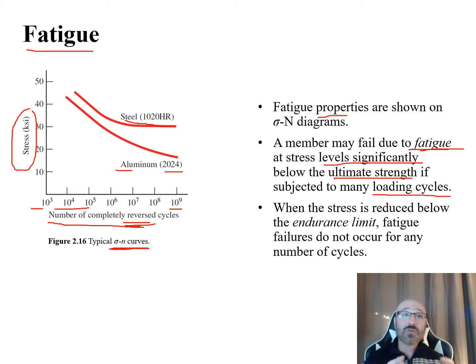This information you can get from the stress-strain curve in these tension tests and life cycle testing. Cyclic loading, in this case, is where you're taking it and reversing this cycle right here. So cyclic loading becomes very important.